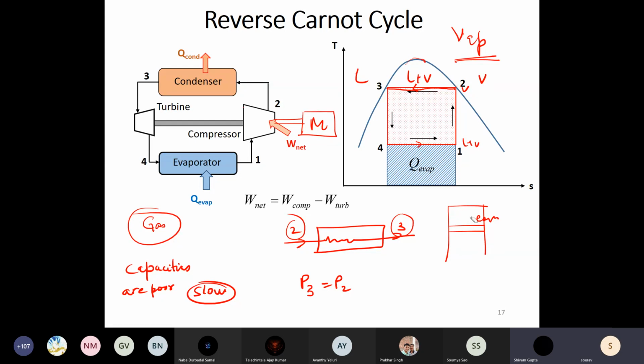An important feature of gas is that it is compressible. Liquid is significantly less compressible. So when we have to compress a gas, what the manufacturers do is they provide very little clearance volume. When the piston is at the top dead center, the clearance volume within this cylinder is very, very small.